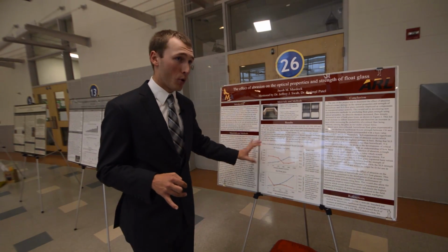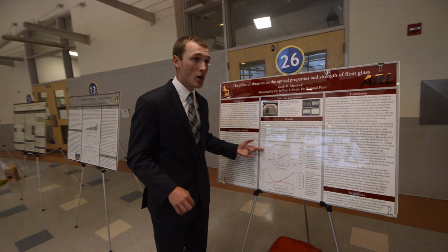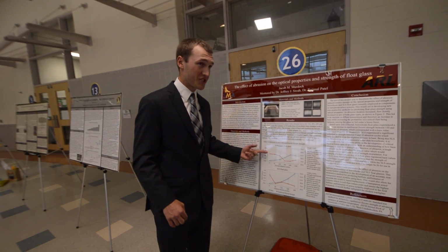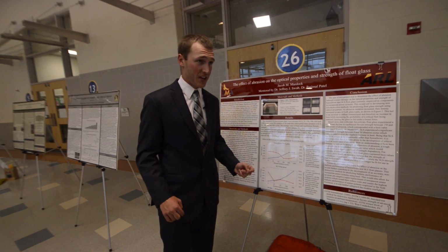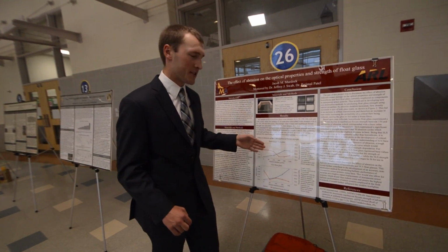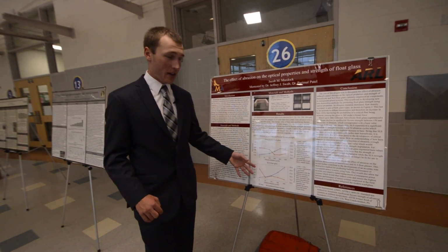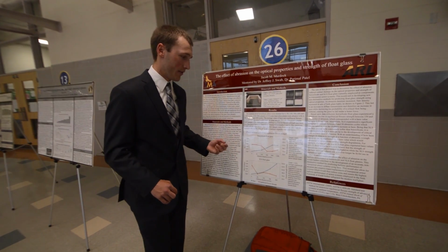As you can see here, Borofloat is much harder than SLS, which explains why it's resistant to initial damage, and it's maintaining somewhat of a baseline strength until between 150 and 300 cycles. At that point in time, when a critical flaw density is reached, the glass plate fails. In SLS, due to its soft nature, it's failing much sooner at lower abrasion levels.